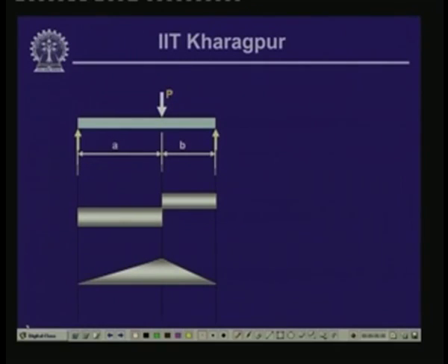You see, this is the shear force and the bending moment diagram of this particular beam, which is loaded with the concentrated load P over the span L, the length of the beam as L. If we have a concentrated load placed at a distance of A, we have the shear force variation. As we have seen, the shear force here is, I am sorry, this is negative, this is negative, and this is positive. For the bending moment, as we have seen, it is positive for the whole region.